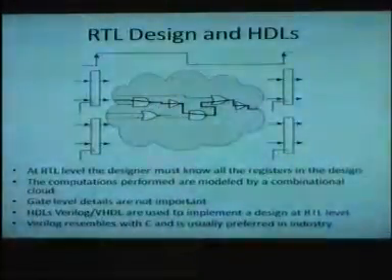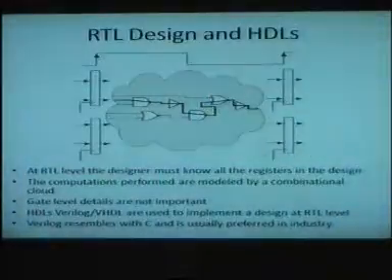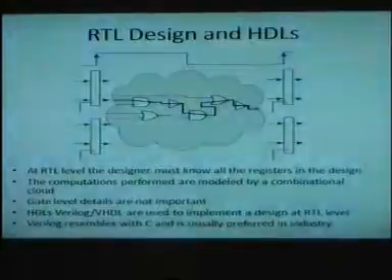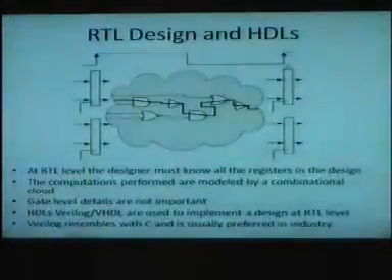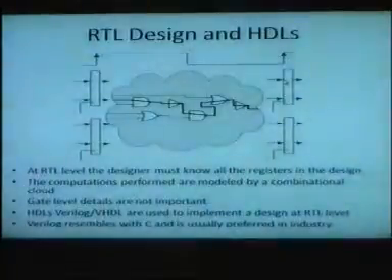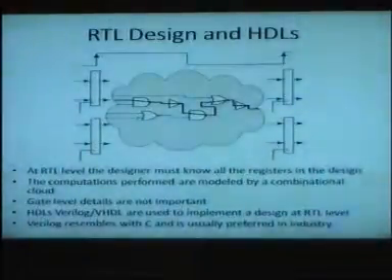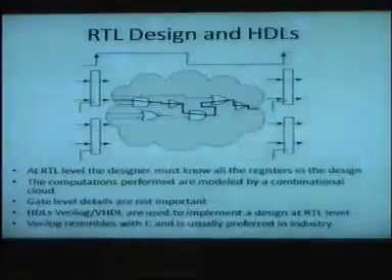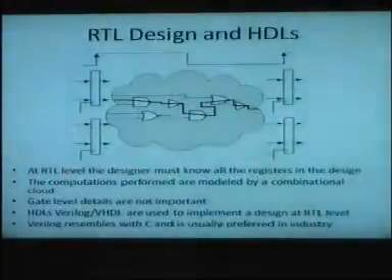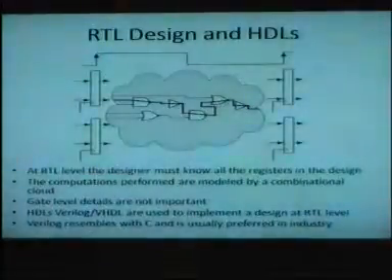At the output, you now have 1 full clock cycle to make sure that your signal gets stable before the next positive edge of the clock. If, for example, you try to run this circuit at a higher clock, the circuit will not complain. It will not say you cannot run me. Definitely you can run a system which is designed for 100 megahertz at 125 megahertz.